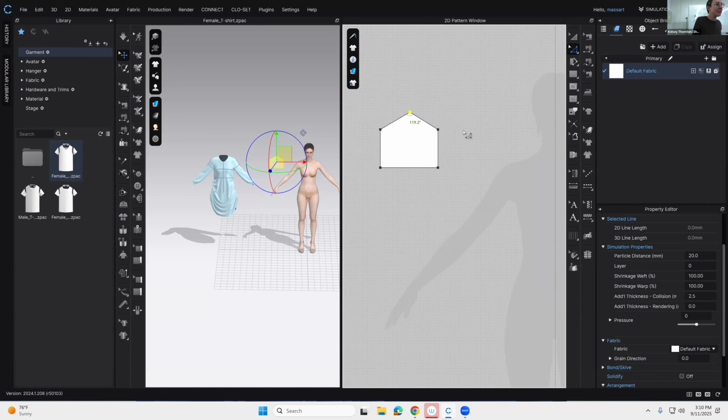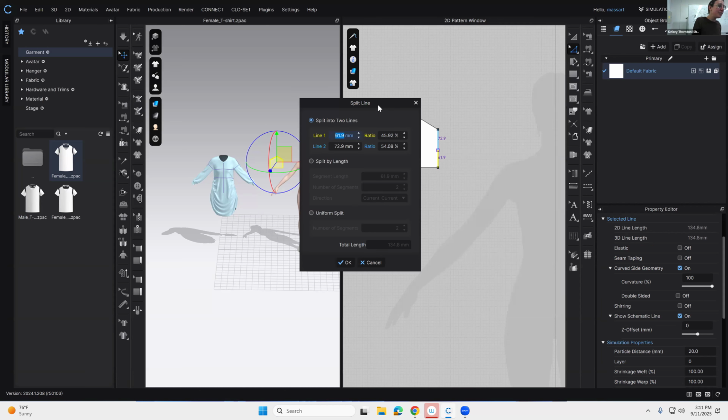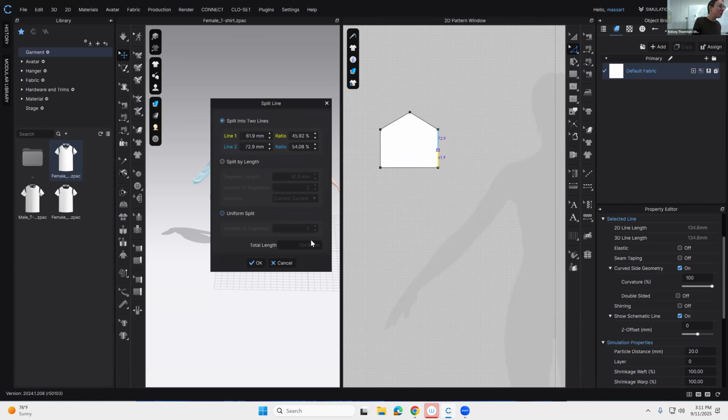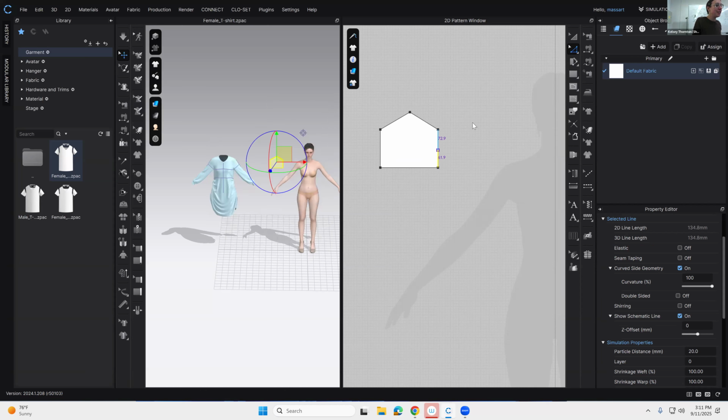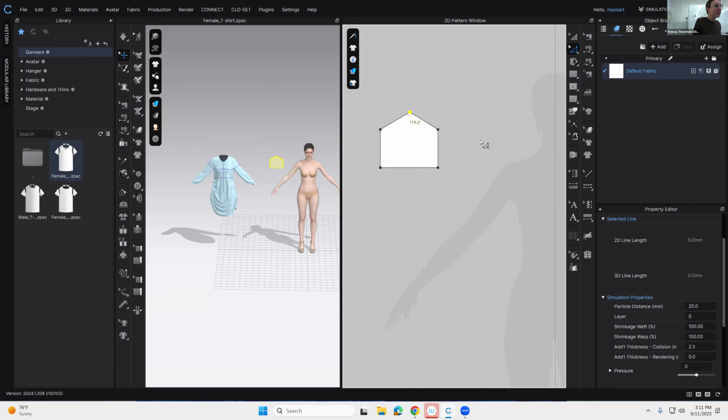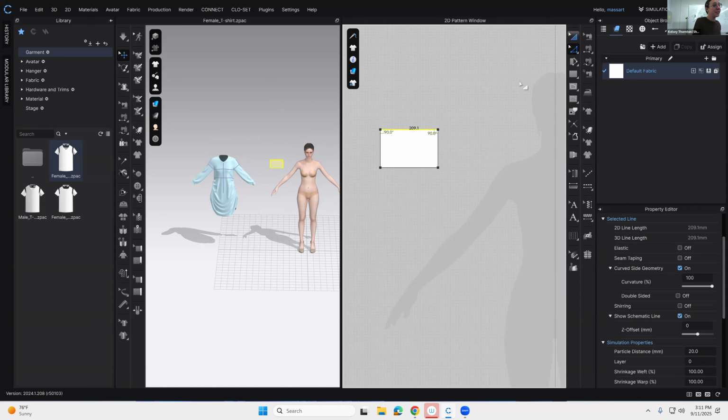Oh, okay. Great question. Wherever you right click, it'll split. Split is also kind of unique because you can tell it to do a uniform split or split with different lengths, so you can get pretty specific with it, but if you don't do anything, it'll just do it. If you leave this setting on, it'll just do where you click. Great question. Other questions right now?